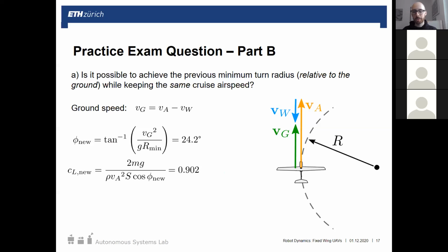So that's why I was saying it's loose. It's a bit of a loose definition, but all you need to remember is out the nose is X body axis. It is normally quite close to being parallel with the airfoil of the wing. And then for the Y axis, out the right wing.